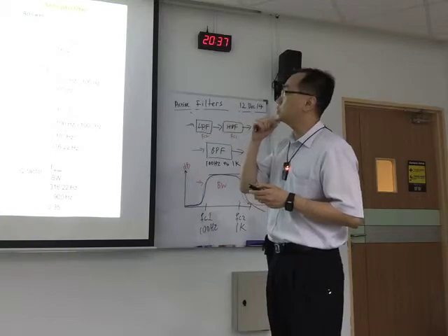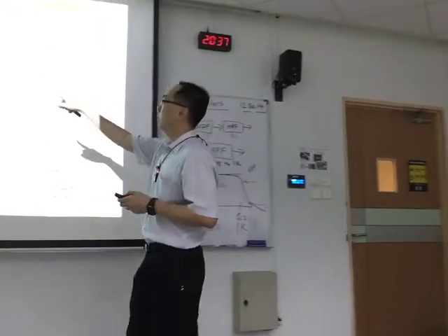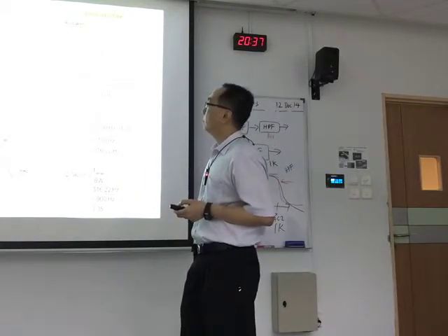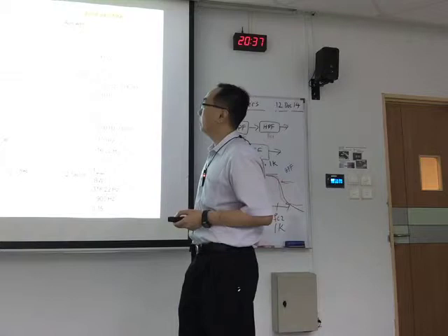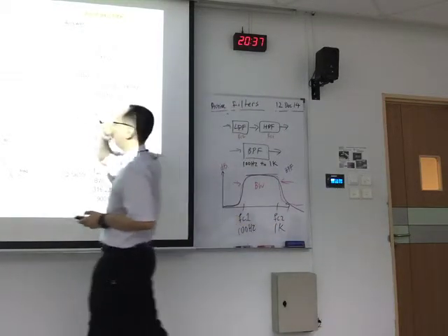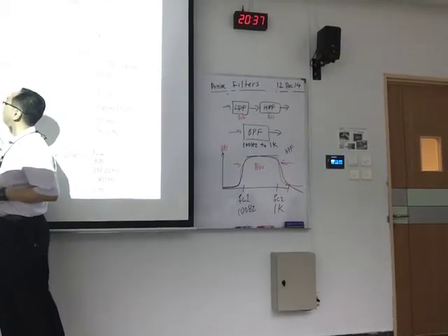I think you have another one. Of course you also can look at part B. It says that the passband gain of this band pass filter is 10 dB, and if it's an AC signal of 500 Hz, always check out the frequency. You don't really care about amplitude, you more on the frequency.